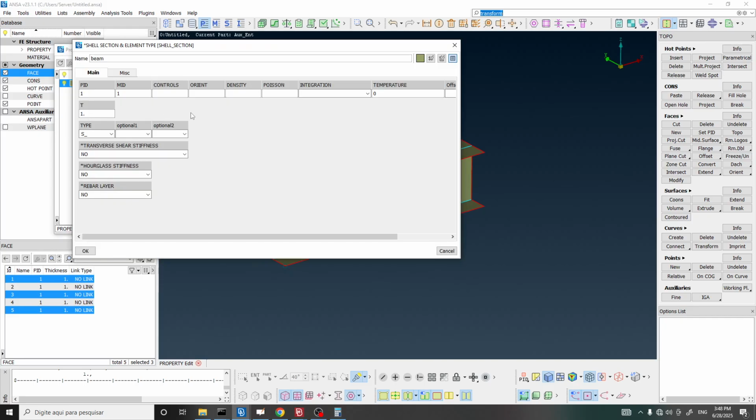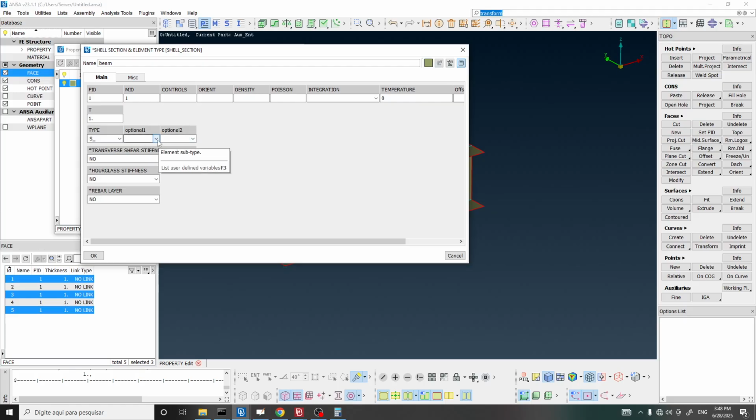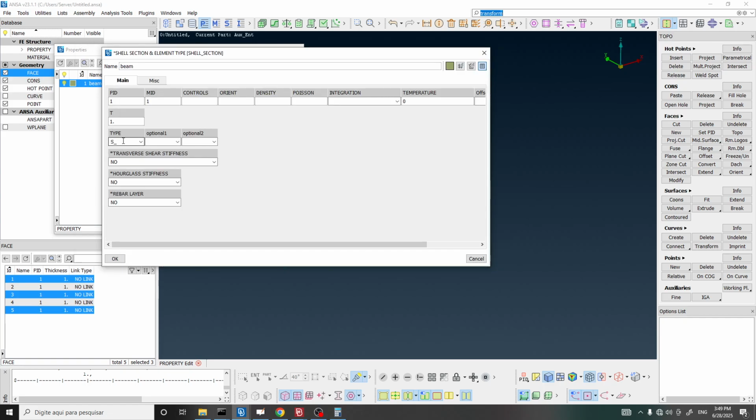So yeah, this is important. The shell element formulation that we're going to use is the fully integrated finite strain shell element. Remember, you can search for the S4 element in the Abaqus manual. This element is applicable for thin shells and also thick shells. We can have finite strains, which is important for nonlinear analysis when we have large deformations. And yeah, that's the main characteristics of this element. It's a pretty good formulation to be used for shell elements.